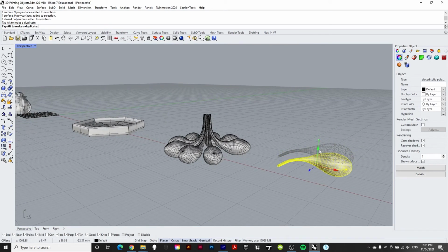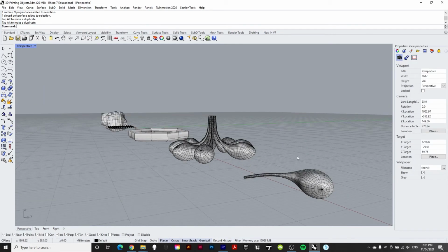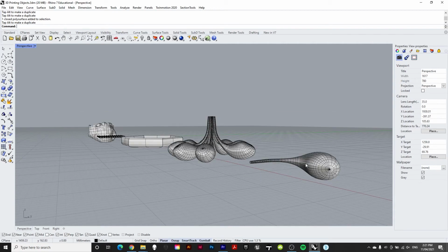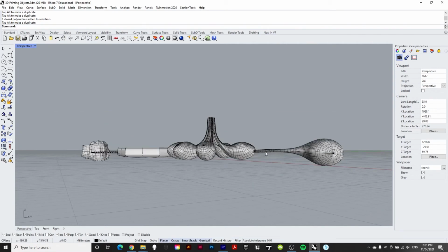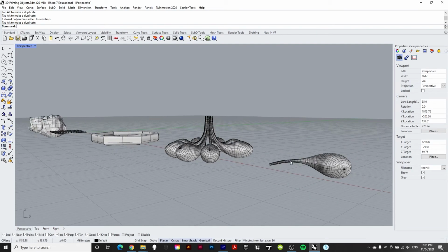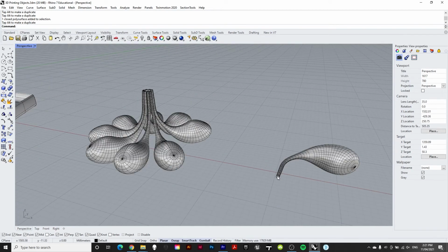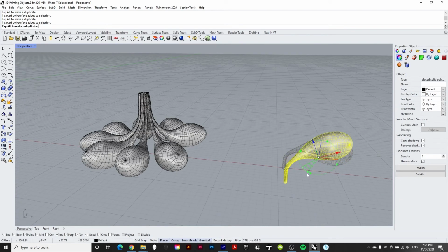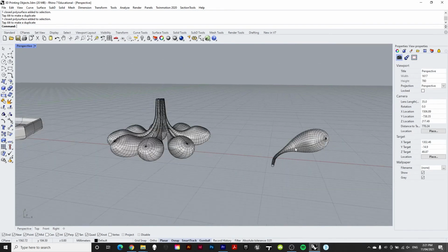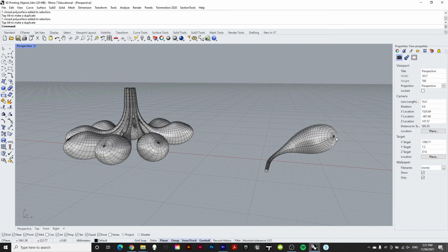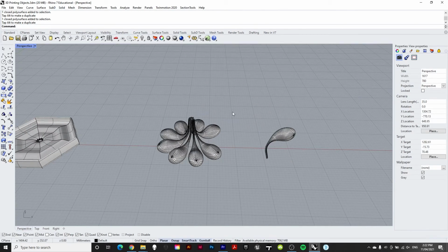So we would flatten this out, lay it on the bed, and you would tell the fabricator that the most important surface for you is the tip of the tulip. So please align all of my supports and my structure along this bend here. And they might say to you, well, this is too small here. It's going to be quite fragile, might snap if we put our structures there. In which case you would say, okay, no problem. Lie that down flat and then just try and arrange my tulip so it doesn't have too much structure on the front. And then I'd be able to sand down this big side here without having to worry about anything on that edge there. We would then do that 1, 2, 3, 4, 5, 6, 7, 8, 9 times.